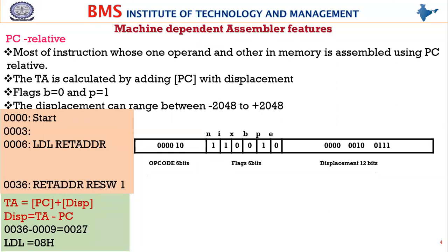So now how to generate the object code for this? This much we have seen in the architecture, but how to generate the object code? We can generate the object code by grouping the 4 bits together. After writing this, we'll group the 4 bits from the most significant bit towards the least significant bit. Whatever hexadecimal values we get will be our object code. Just have a look. We have grouped the first 4 bits, which gives 0.